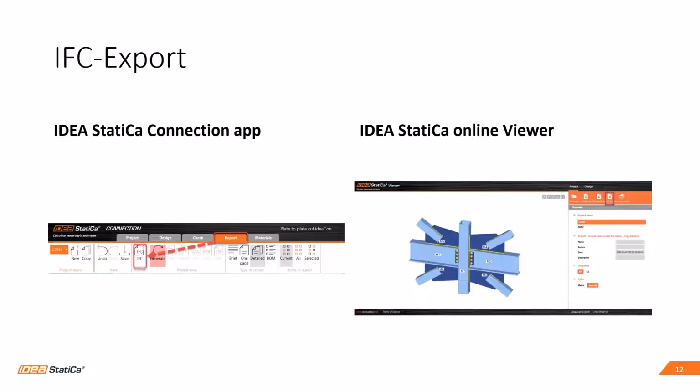Okay, let me change the slide. All right, just like a reminder, you can create the IFC file either from IDEA StatiCa standalone or IDEA StatiCa in Checkbot. That example that I showed you was by exporting the IFC from the report tab. So that is always an option.